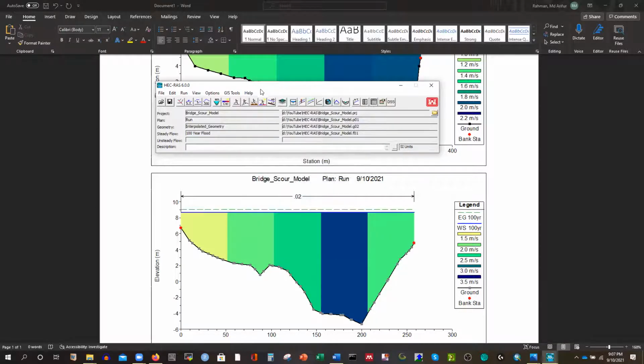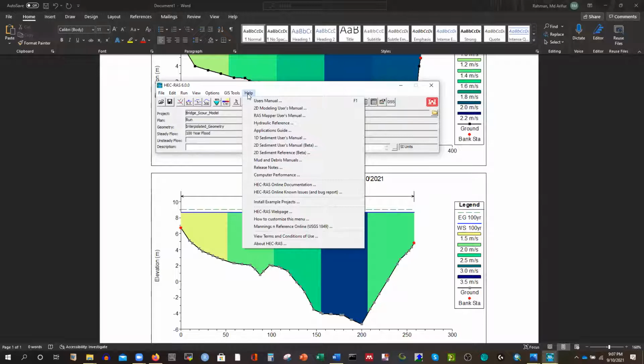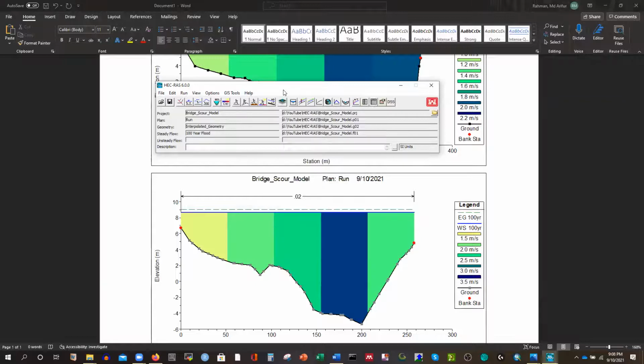So you have everything there, right? You can do that. So these are the options you have to even explore by yourself, but I'm going to show you only the basic thing, that how you can start developing or setting up HEC-RAS model from scratch. So that's the one way to set up. So we have one model that is basically 1D model with steady run condition for a specific location, right? For 100 year of return period of water level and flow rate.